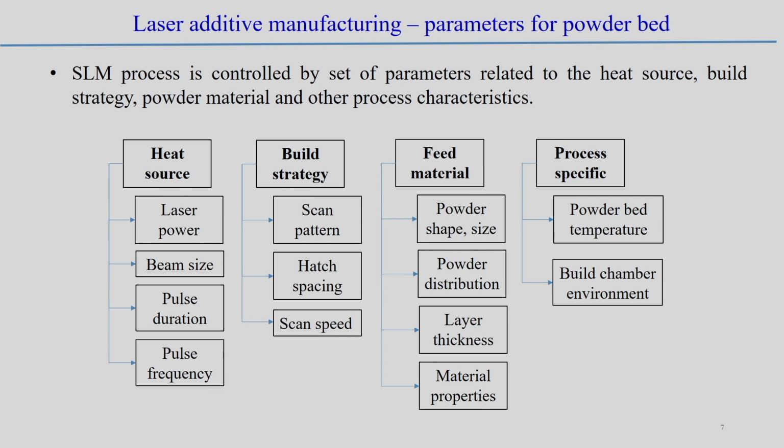Scan patterns means, for example, moving continuously in one direction, or moving in a zigzag way, or how to handle it if there is a curvature. So, how can the motion be controlled when depositing over a curvature? That kind of scan pattern and scan strategy is required in these cases.